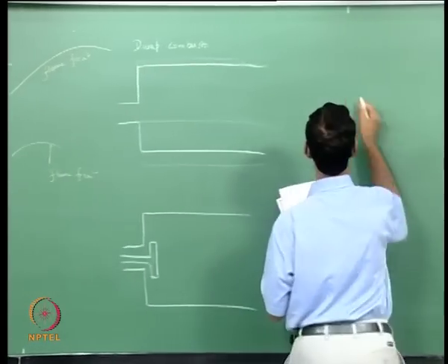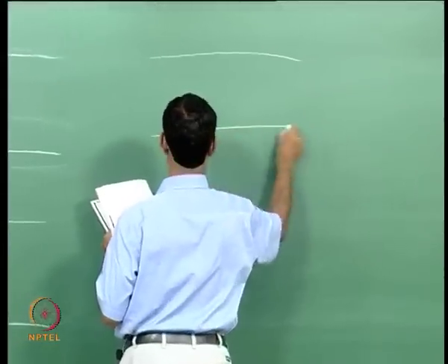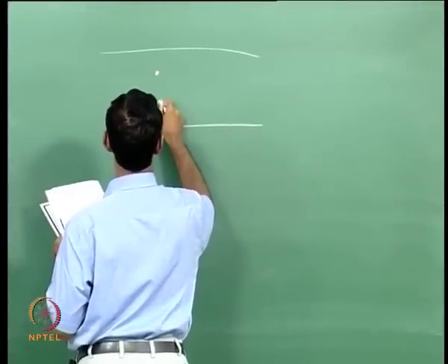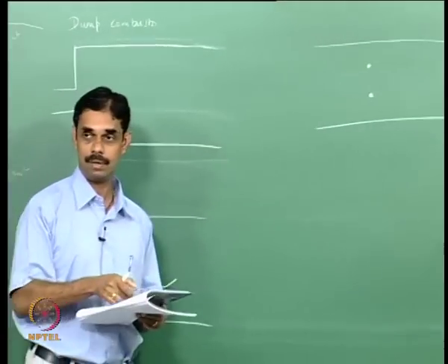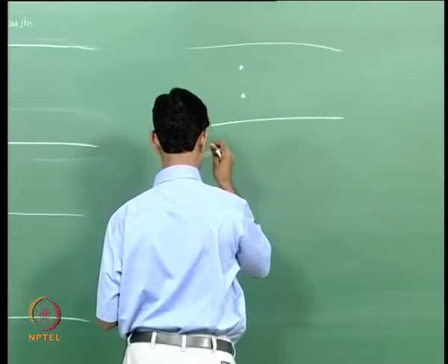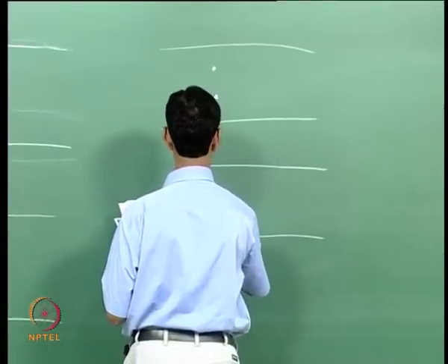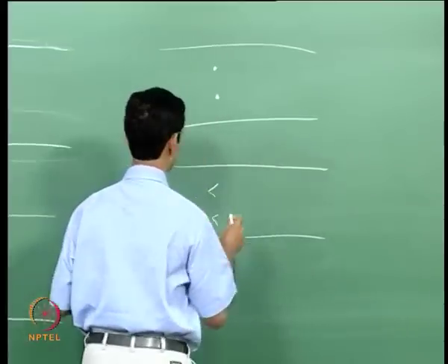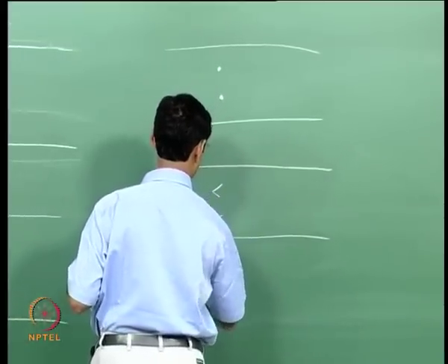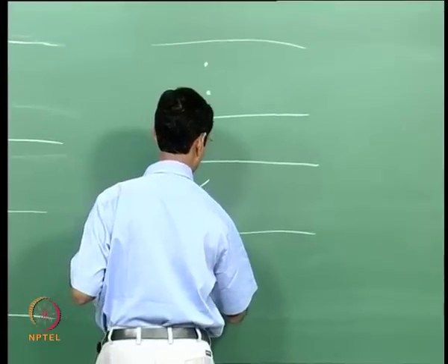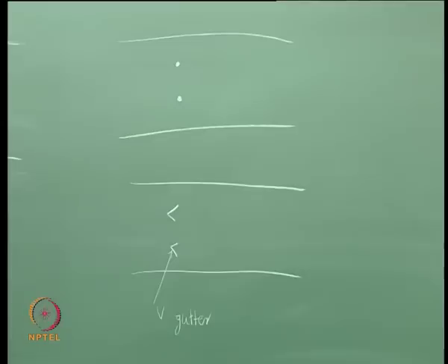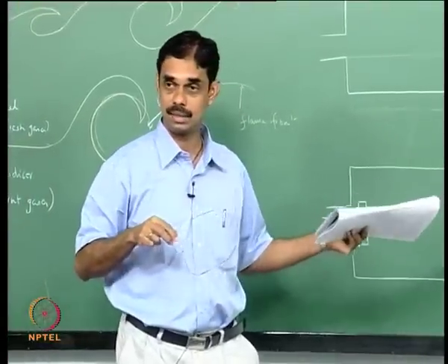Other variations which you would see are some kind of wire or cylinder which will hold the flame in its wake, or what are called V gutter stabilized flames, which are sometimes used in afterburners of aircraft engines. These are practical combustion configurations.